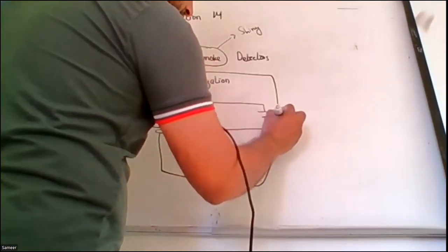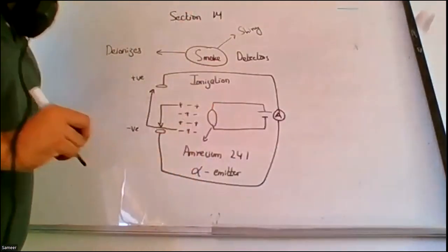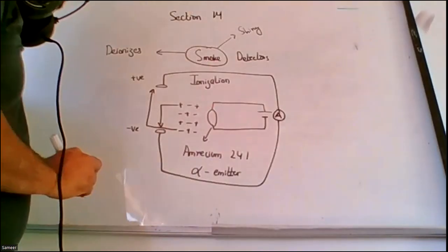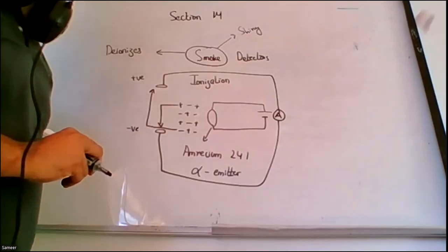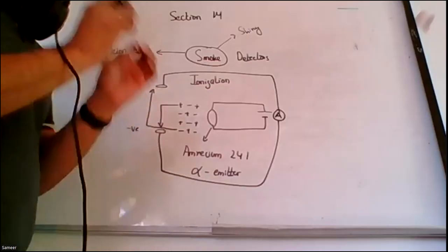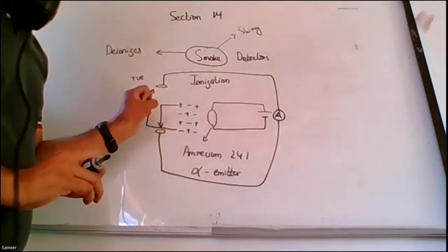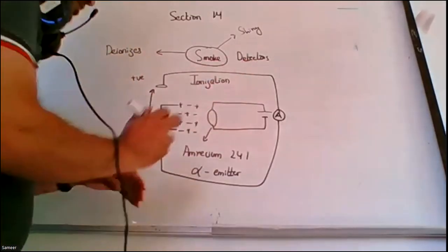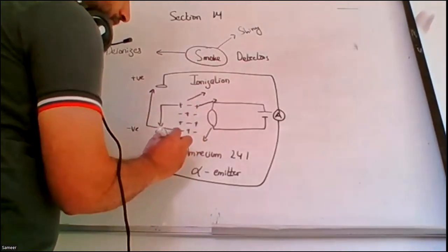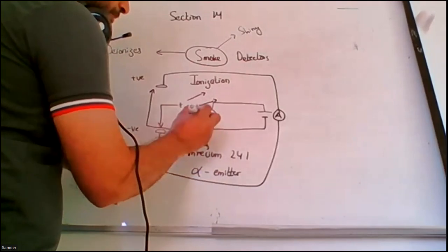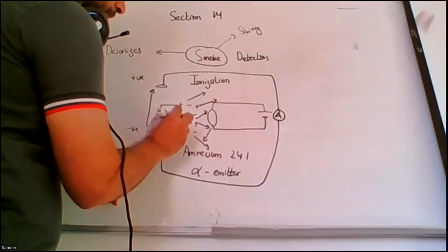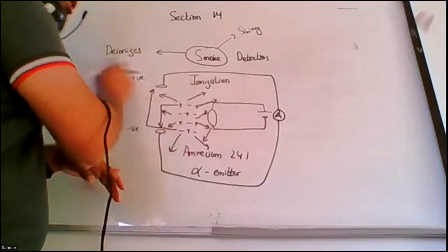Okay, this current is being continuously measured. Now what happens at this point? Whenever smoke enters the chamber, it creates a blast of deionization. It means that as soon as it enters the chamber, it will blast the ions off in various directions. The positive and negative ions will be flowing in all directions, away from the charge plates. Not near, away from the charge plates.